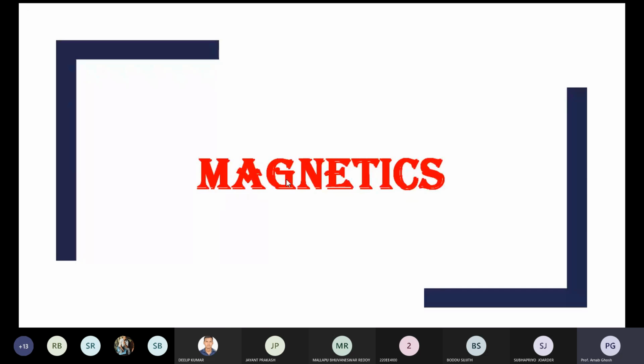Basically, if you use the laminated core, the soft iron laminated core, is it possible to work at 100 kilohertz? No, it is not possible. So you have to select a magnetic material that is capable of handling 50 kilohertz and beyond. That's why we switch to the ferrite magnetic core.